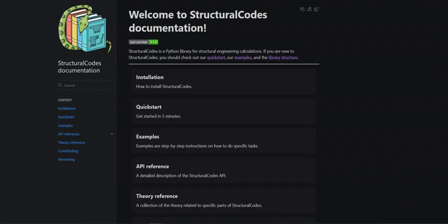And as you mentioned, we just briefly touched upon all these functions that are present in the design code layer here. So we have functions for shear design, we have creep and shrinkage, we have crack width calculations, etc. These are not directly tied to the sections because there's not an easy tie into there, but some connections will come in the future, I think. But I think you will have the basic ingredients for building at least a notebook that could be used as your go-to design tool.